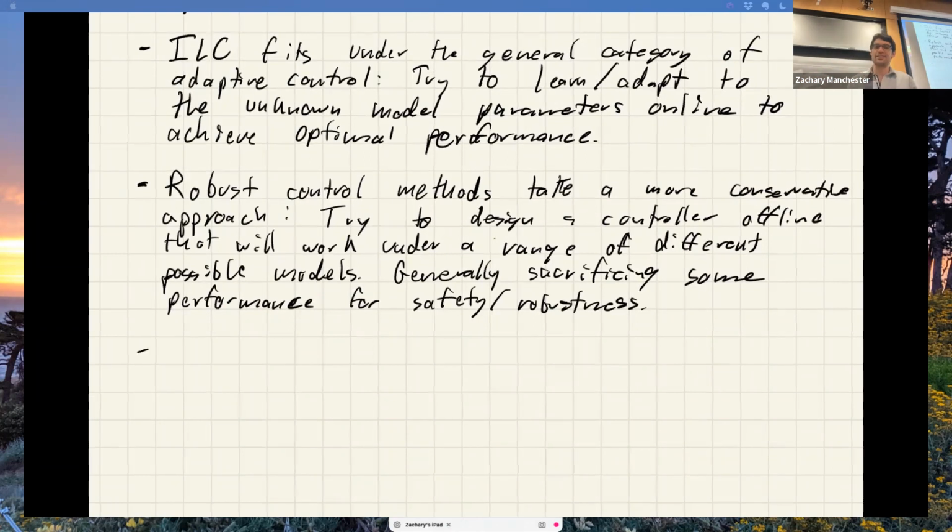The history on this is super fun. I think I teased this previously. If you look back at the history of control, early work on LQR showed strong robustness. Basically, if you do full state feedback and you just have an LQR controller, people actually proved robustness guarantees for vanilla LQR. So people thought that LQR was sort of magic and had these natural robustness properties, and we didn't have to worry too much. If the model was a little off, LQR was still going to be fine.